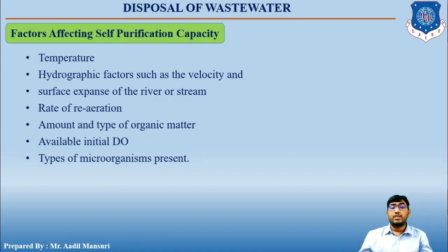Now, in a slow moving stream, the surface water is not being turned over and the stream tends to flow in distinct layers. At the air liquid interface, the water is saturated with oxygen, which can mix with the oxygen deficit layers only by slow diffusion. And the failure to replace the oxygen being used in the lower region of the stream allows anaerobic condition to develop.